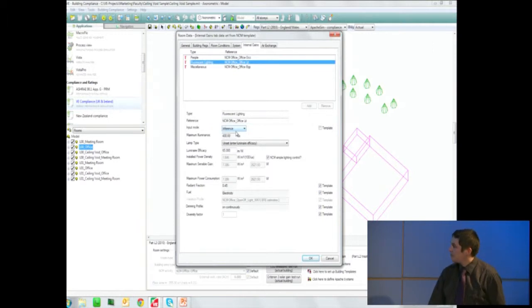I think for a lot of users, these have often been left at the default values, largely because they were being asked for a lighting power density value that, at the moment in time they were working on the project, they just didn't have available. And I think it was putting them at quite a disadvantage. I think now, at that same stage, I would be inclined to use the efficacy input value, where I could then target a level which is competing with the notional building.